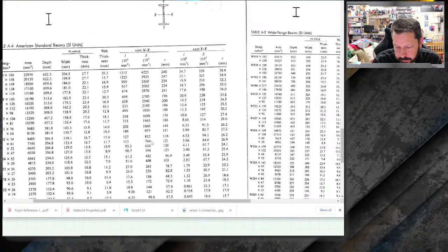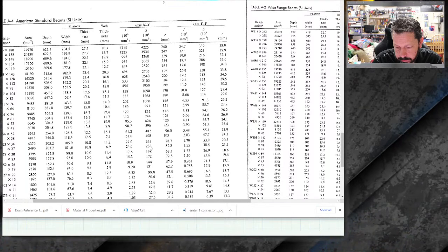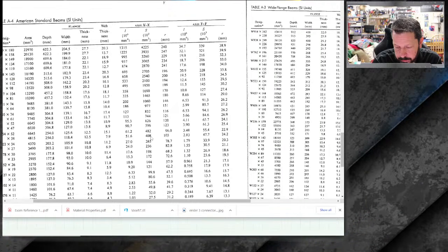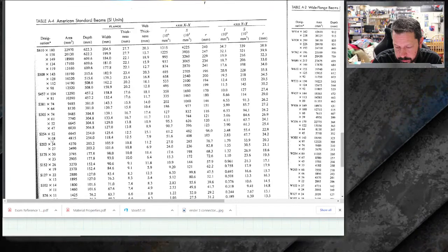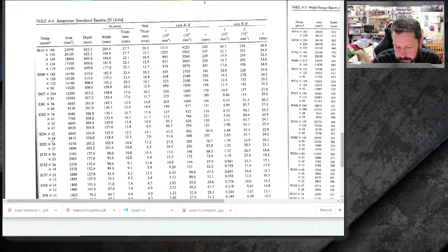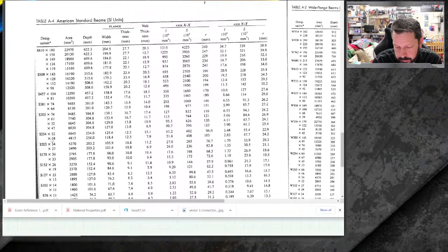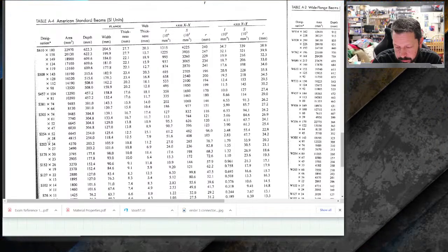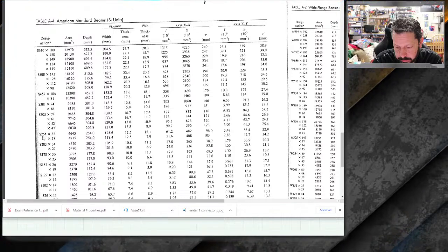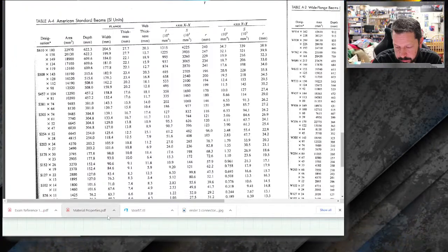These are really big, so 285, it looks like the smallest one is this 408. So that is S254 by 38. Is there anything lighter than a 38 in this S column? No, there's not. So of the S beams, 254 by 38 works.